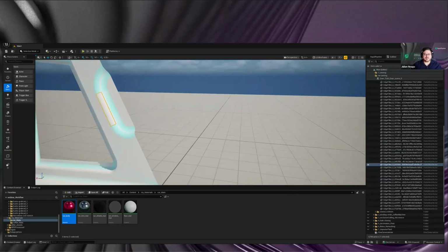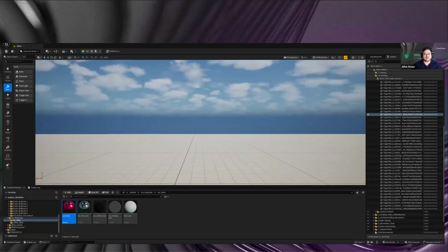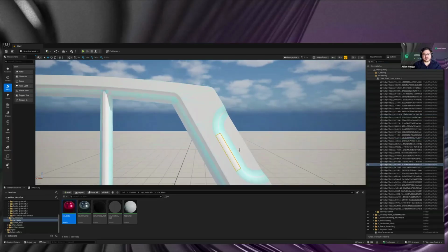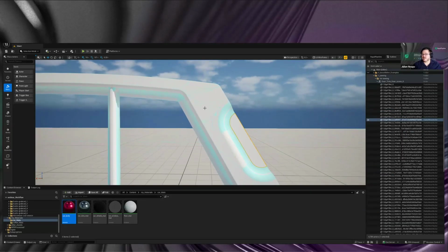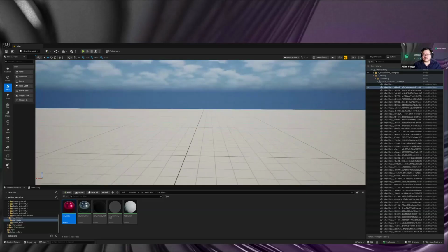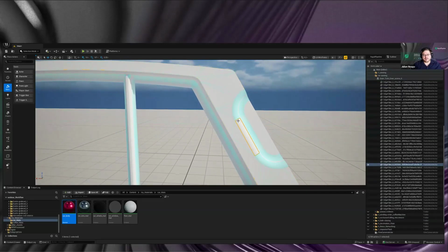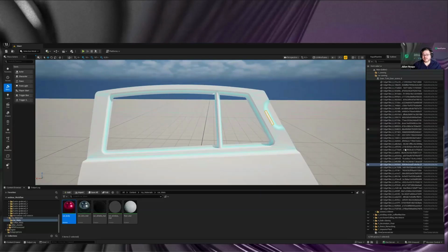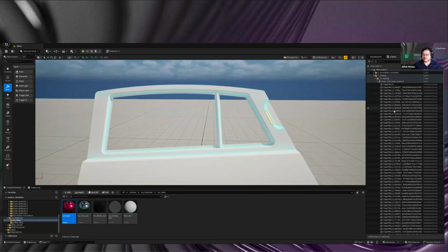So you have all these different resolutions, and they don't really fit together very well. If you would take them all and then decimate, you get cracks, and you have real problems. And a simple vertex by distance merging operation, something you could technically do as well, would not necessarily help here, because we're ending up with a lot of T-junctions with a lot of vertices which have no correspondence on the other patch, for example, because of the resolution difference. So yeah, this is basically a nightmare for any further processing, even in visualization use cases.